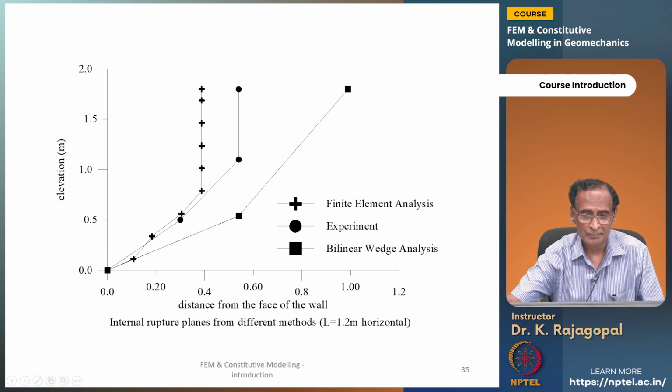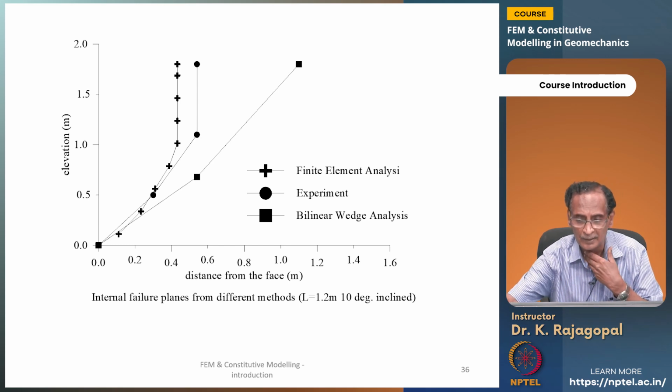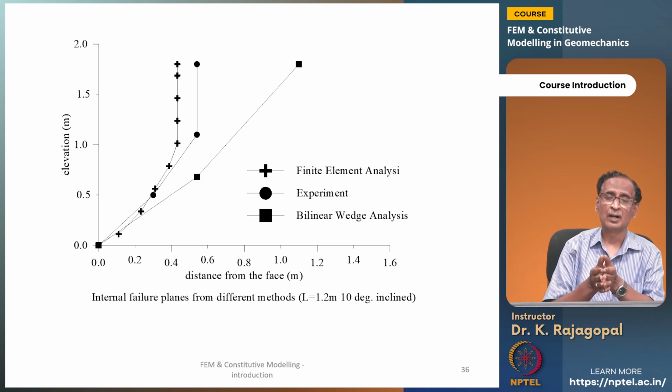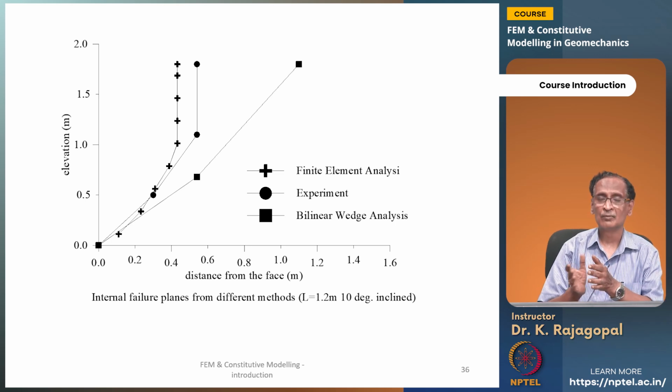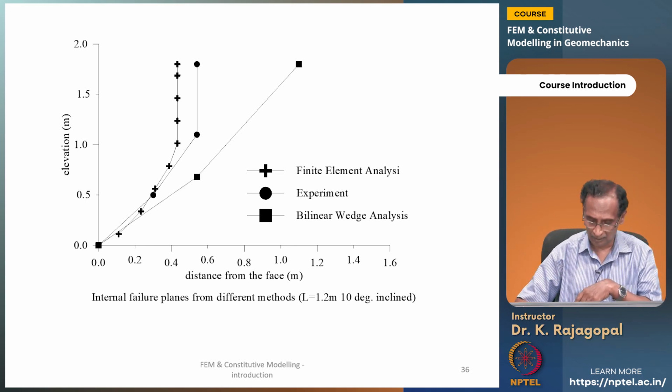It is totally different, and this particular one is the measured one from laboratory test, and this is from our finite element analysis, and different for different inclinations and different lengths of reinforcements. And here we see that our finite element models are able to replicate the real behavior, and they are able to show the influence of the length of the soil nails, their inclination and their load capacity.